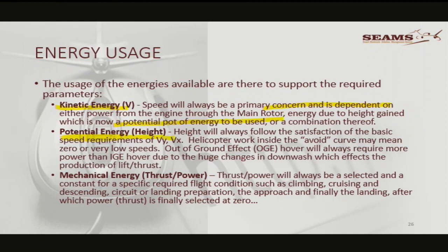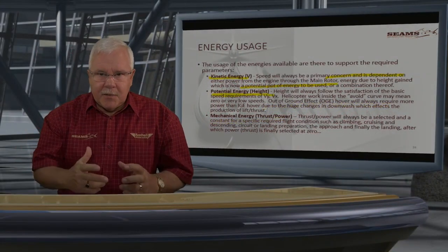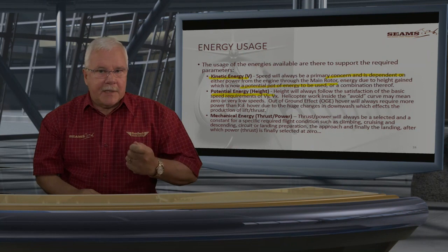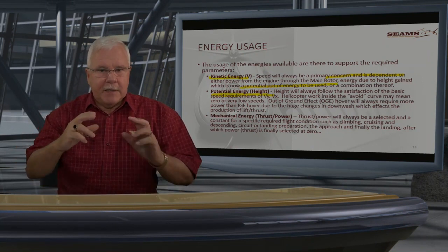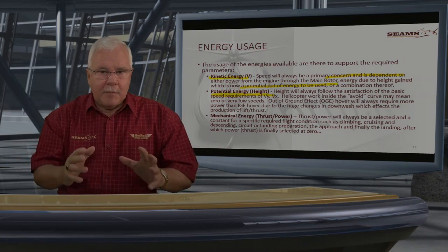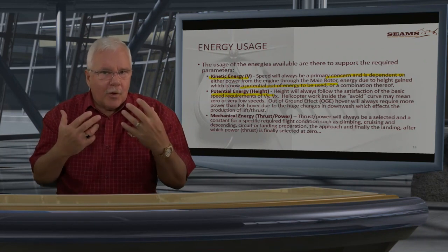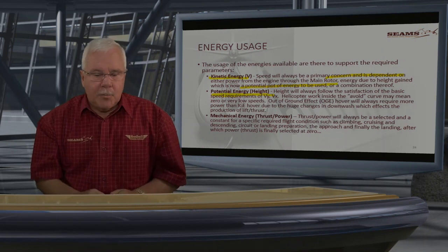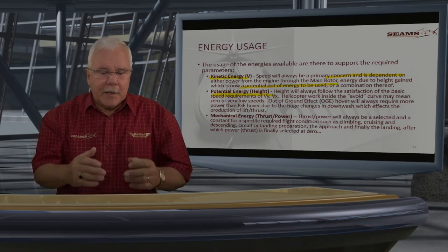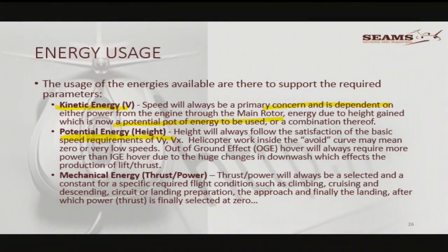Now, you're going to say to me, but what if I climb vertically? Yes, you can. You can use all the excess power and don't have to put it into speed, and you can put it into height in the hover, in a vertical climb. No problem. That's not how we normally operate, except if we get airborne out of a confined area or something like that. But eventually we're moving from point A to point B. But yes, you could say that we can put it directly into potential energy. That's why it's called a helicopter.